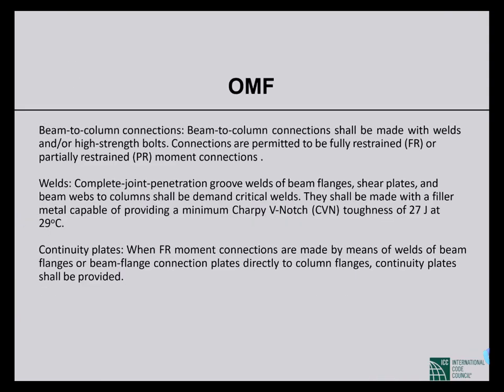Beam to column connections shall be made with welds or high strength bolts. These are the seismic provisions of OMF. Remember, there are systems where we don't need to follow these provisions either. We can design without following these provisions. In that case, we have to consider R of 3. But if we take these provisions into account and design OMF, then the value of R will be like 3.5, something more than 3. So that's the difference.